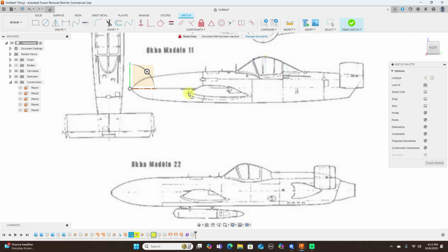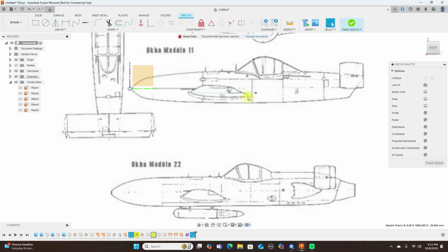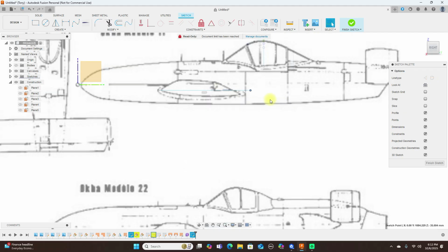So I'm going to create a line. Then look at this from the top. Okay, this needs to come back just a little, it looks like. Now, it probably changed here and went straight up instead of staying down here, which is no problem. We'll just leave it as is. As you saw earlier, this was down here. So now I'm going to use a fit point spline and do somewhat of an airfoil here. And like I said, if you have one that you want to use, go ahead and use it.